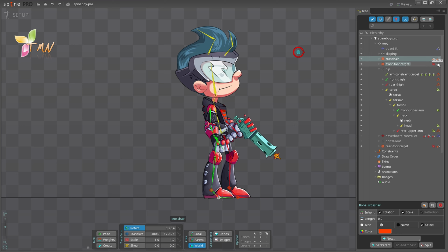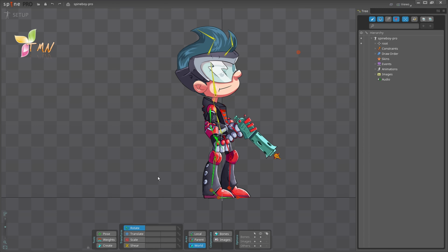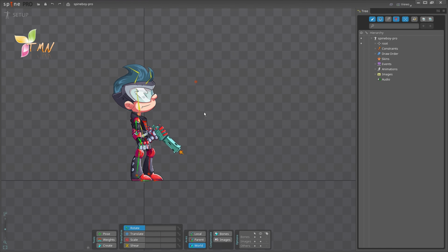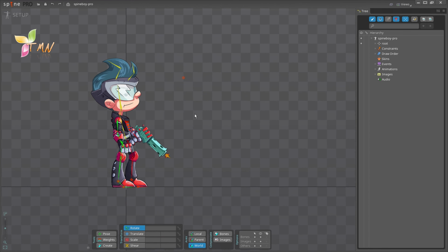Next let's go over how to navigate around through your document area. So you're going to need to be able to click and drag around and also zoom in. The way you click and drag is you just right-click with your mouse and then drag around. Then the way you zoom in is you hold down Control, then right-click and either drag up or drag down. If you're using a mouse with a rolling scroller, you can go ahead and just scroll that back and forth and that will zoom in and out.